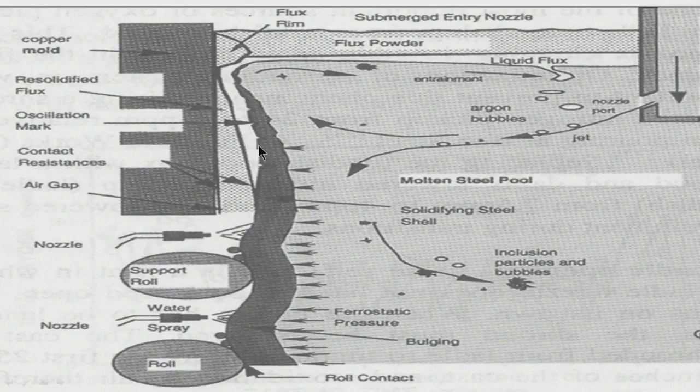shell sticking. So, this mold movement we call mold oscillation, it is going up, going down. There is a frequency at which oscillation will take place, and there is an amplitude, to what extent it will move up and down. Because of the turbulence, the liquid steel level at the surface here should not move up or come down very much, because the turbulence has to be controlled.